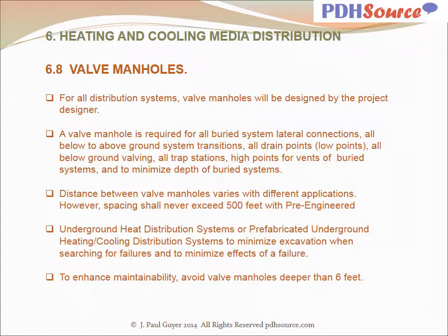Distance between valve manholes varies with different applications. However, spacing shall never exceed 500 feet with pre-engineered underground heat distribution systems or prefabricated underground heating cooling distribution systems to minimize excavation when searching for failures and to minimize effects of a failure. To enhance maintainability, avoid manholes deeper than 6 feet.